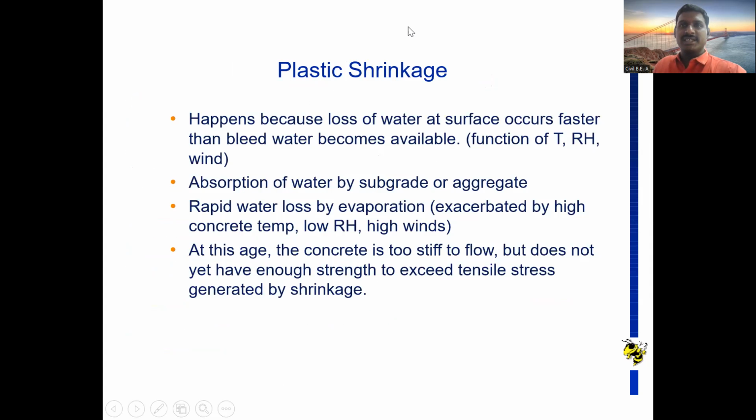So what is plastic shrinkage? If you see here, plastic shrinkage happens because loss of water at the surface occurs faster than the bleed water becomes available. This phenomenon takes place, and due to that the plastic shrinkage will happen.